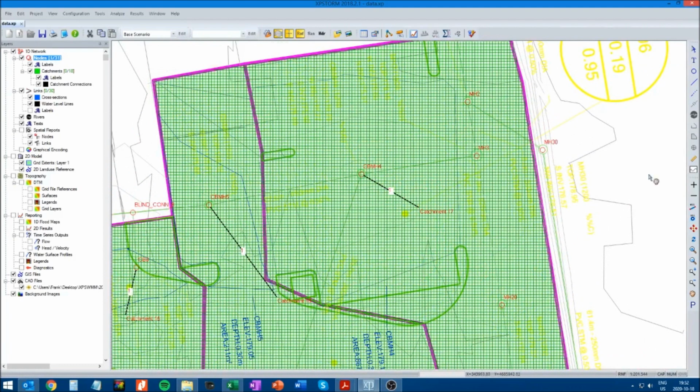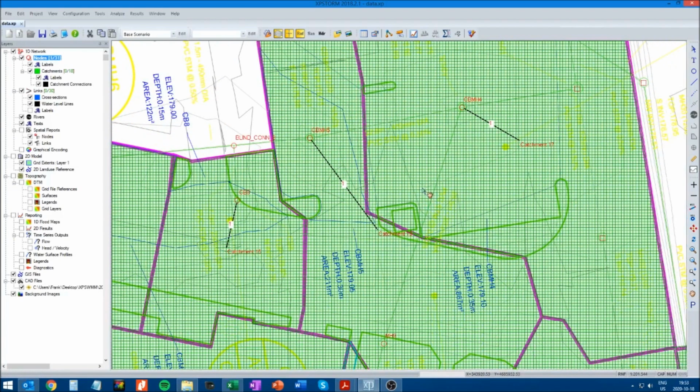Okay, here's a bunch of them. So this manhole is not, so remove it. This manhole, this one, this one, and this one is okay because this CB is getting runoff from catchment 7. And do that with all the other structures. So this one is getting runoff, so is that one. This one's not, so remove it. And so on.